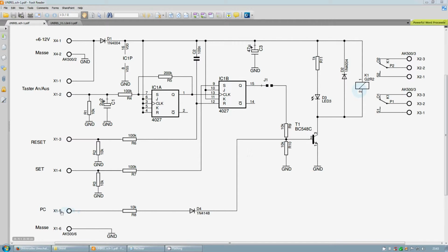If you want that a positive signal here always switches your load off, then just reverse the usage of the normally open and normally closed contacts. In that case, when you have a positive signal, the transistor switches on, the relay is engaged, but now, because you have connected your load to the normally closed contacts, it will now change over to the off state.